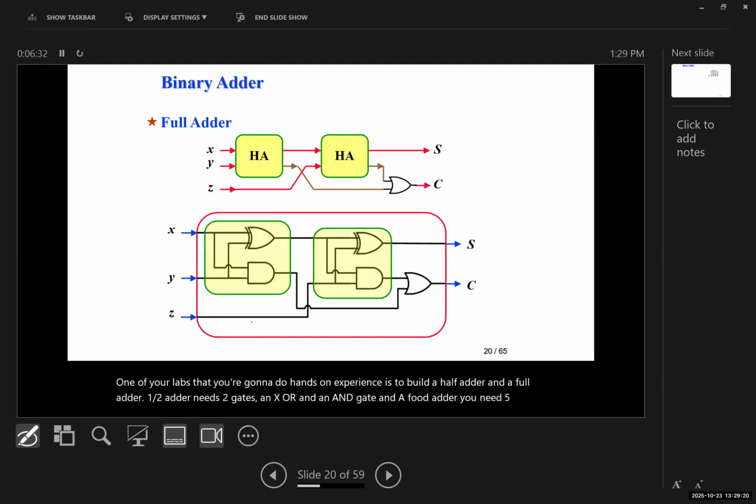And this is an IC which uses a 4-bit carry look ahead adder. The propagation delays of C1, C2, and C3 are equal, meaning it doesn't need to wait for the answer of C1 to come out to be able to calculate S2 and C2 and then S3 and C3. It could do all of that at the same time using this IC.